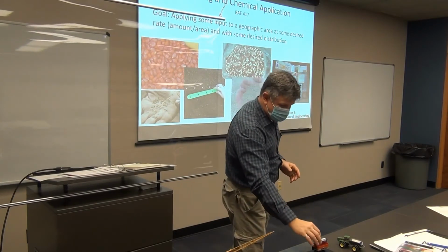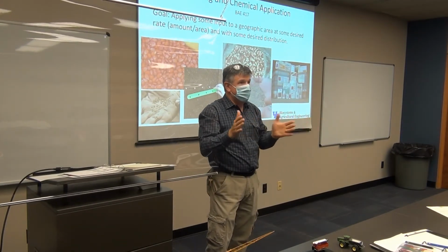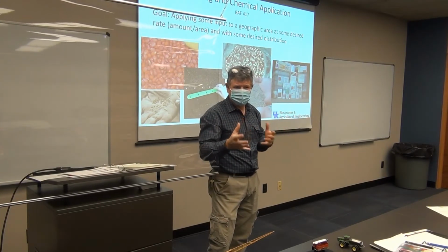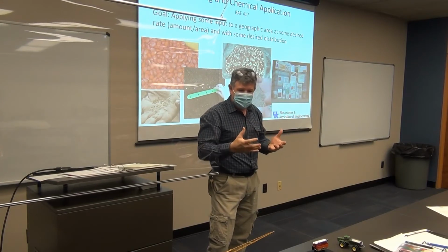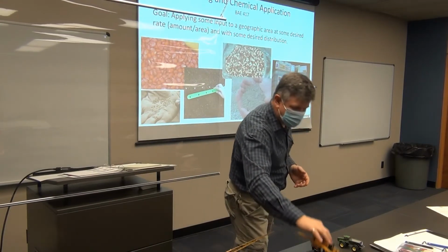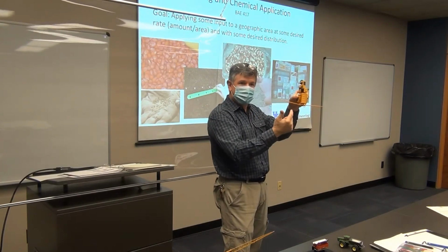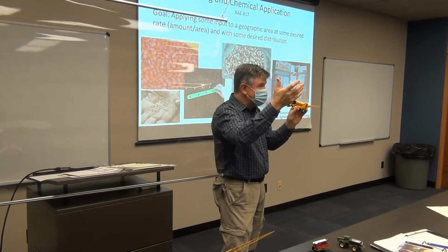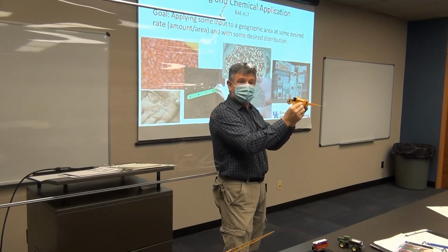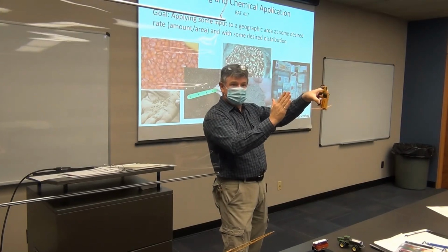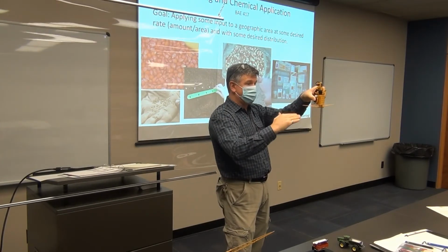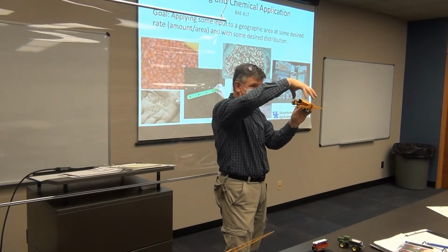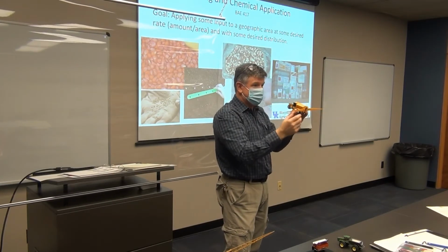And they're actually able to do some control, what we call automatic section control. I don't think I went into that technology in the videos very much, but when you think about automatic section control, if I have a wide hardware boom that has certain outlets, I can figure out mechanically, you guys are engineers, right, I can shut some of these off. So if I'm going across the field and there's some obstruction there and I don't want to put that material there, I just shut some of these off. I can have valves, I can do a lot of different things to shut that off, not a big deal.